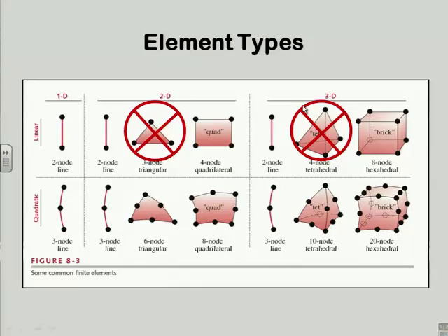Unfortunately, in my experience, and I think this is changing because the code's getting more and more sophisticated all the time, a lot of the FEA solvers that do auto meshing, they create the mesh for you at the push of a button, which is really neat. You take your solid model from SolidWorks, Pro-E, whatever, and you move into the FEA piece of that software, and you tell it mesh it, and it throws these things in. It usually defaults to the triangle or the tet. So it's giving you the lousiest potential element as the default. So you may want to go into the menus and say, no, no, I don't want that.